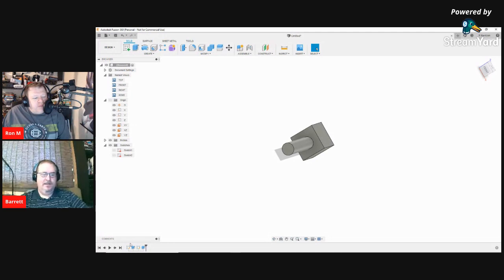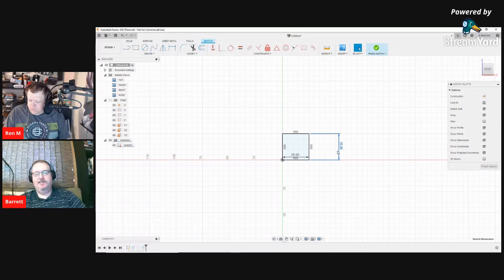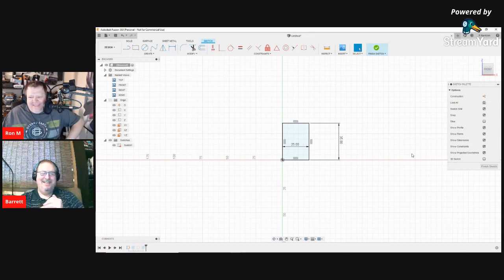history. Now, if I click on that, would that revert all the way back to the beginning? Yep, so right-click on that right now. Okay. And then edit sketch. So now, if you change that one dimension there, make it 35 or something. 35, you say? Okay. Yeah, why not? I was thinking 45, but 35 then. Go ahead, it's your drawing. And then just finish sketch.